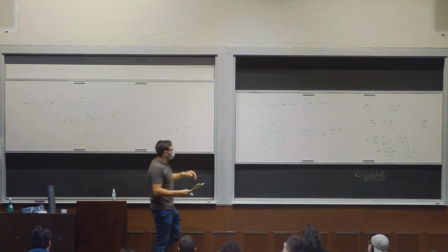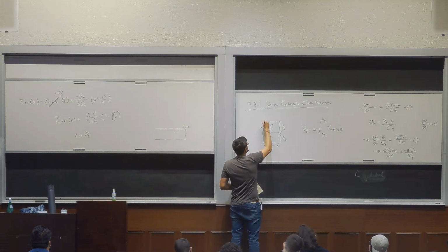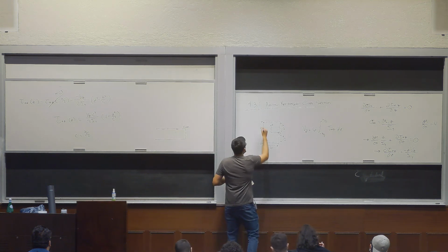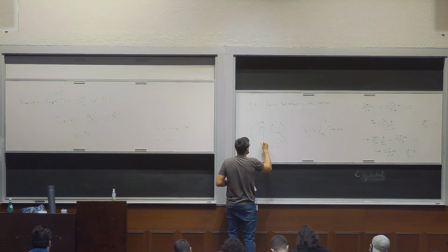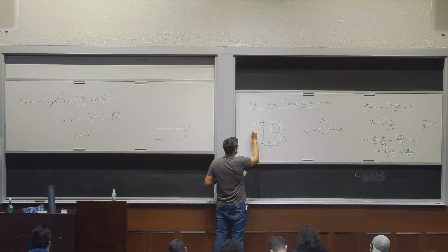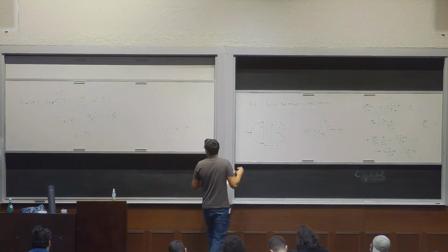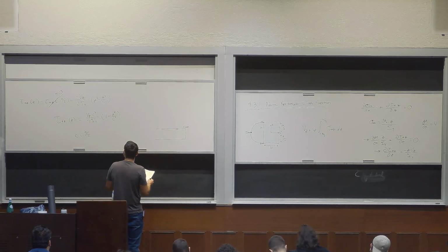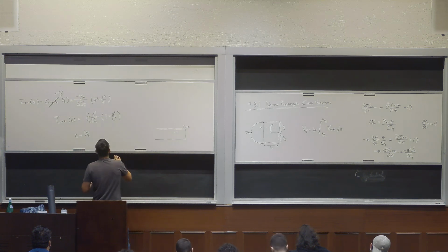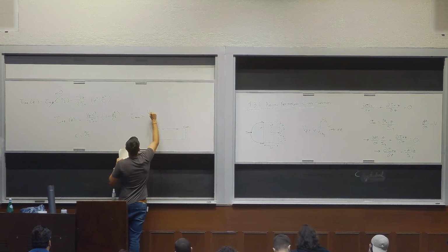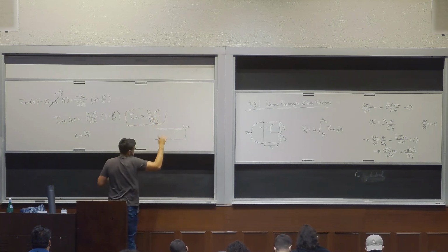Okay, so we go back to our cross section. We know that tau xz equals 0 here, and it equals 0 here, and we know it's a quadratic distribution. The distribution is going to be like this, and the maximum is going to occur right at the center. So this is tau max. The value for that, we basically have to plug in y or z equals 0, which would result in just tau max equals Vz c squared over 2 Iy. So that's the maximum, and it occurs at the center.